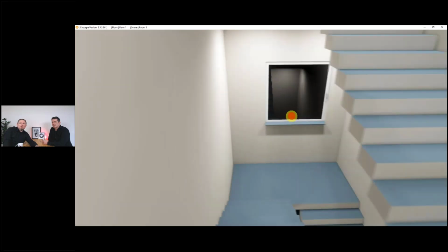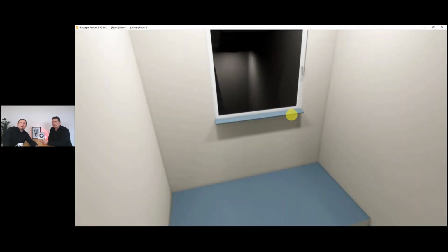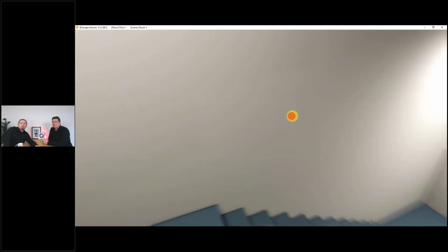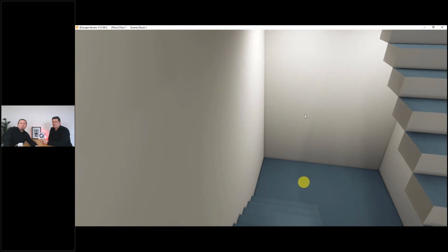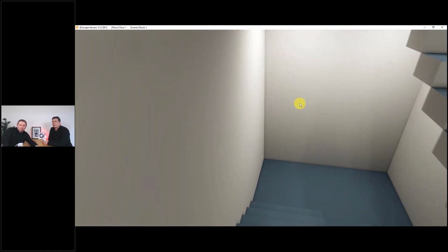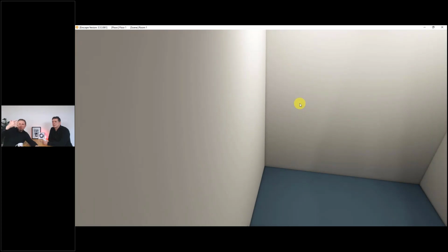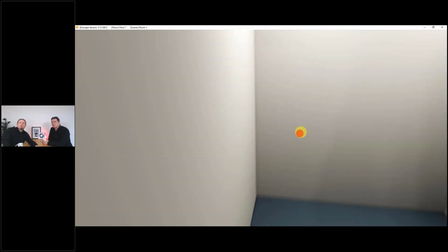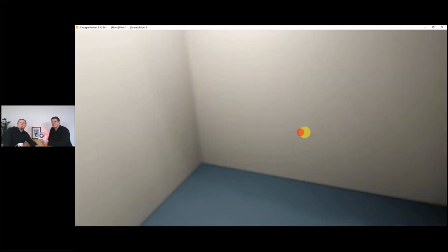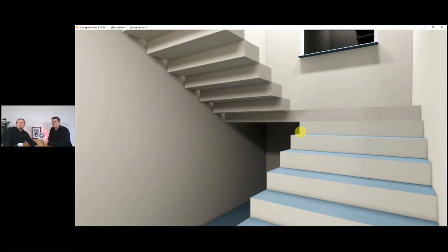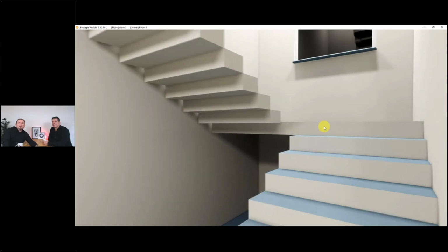The same if you are walking down or up the stairs, and check the walls. If you walk through this wall, it would not be nice to have a luminaire at 1.60 meters height in this area, where you're staring at it while walking down, in the light output, where you are getting glared. So it's hard to say if it's 25 for UGR, but you should think about the observer, the user of the staircase.